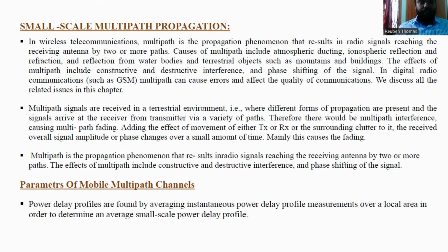Multipath is the propagation phenomenon that results in radio signals reaching the receiving antenna by two or more paths. The effects of multipath include constructive and destructive interference and phase shifting of the signal. The parameters of the multipath channels, or the power delay profiles, are found by averaging instantaneous power delay profile measurements over a local area in order to determine an average small scale power delay profile.